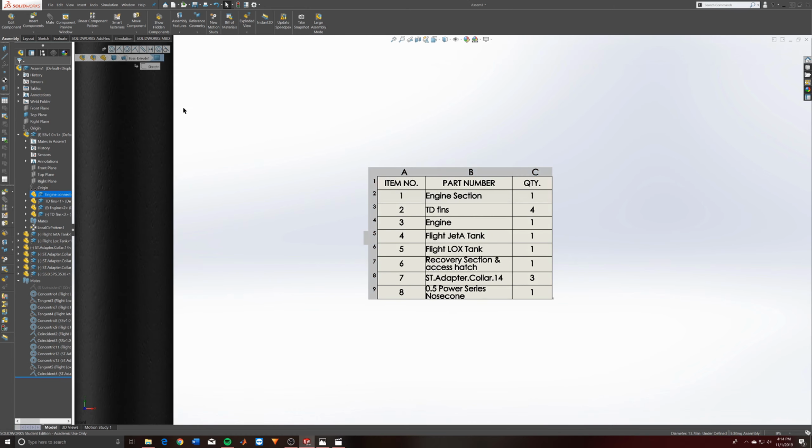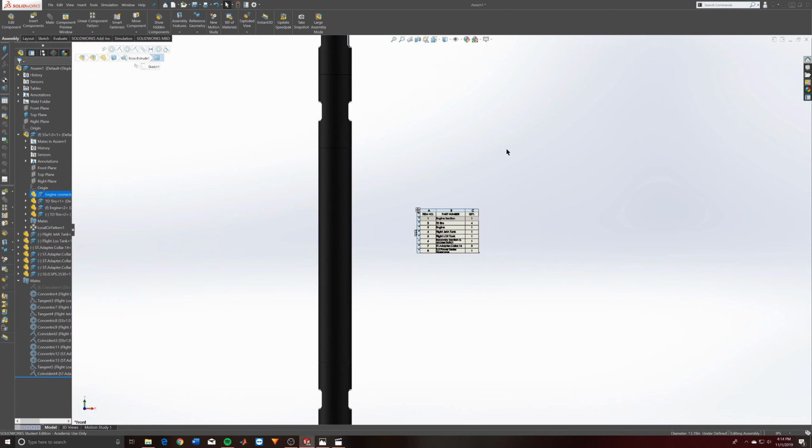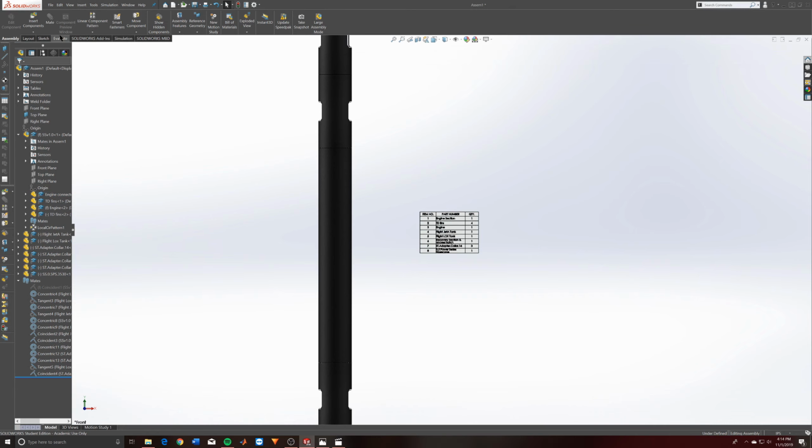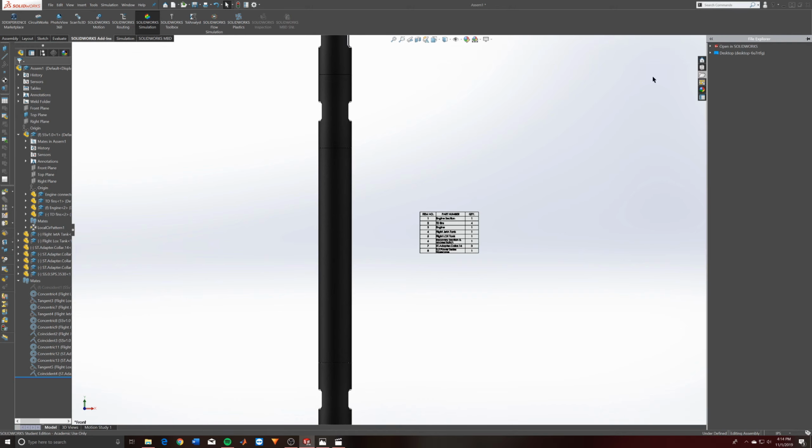Because in assemblies here, using your toolbox, add-ins, yeah, your toolbox here, which I don't have enabled right now. If you know you're going to use 1/4 inch or 1/2 inch bolts, and you have all the holes, you can place all those using this toolbox feature right here in SolidWorks.